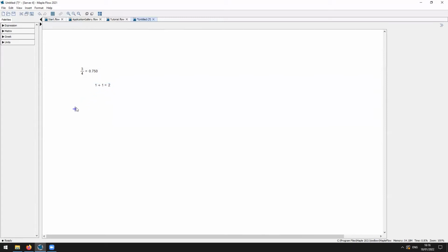So far, I've just created two very simple math containers. I can also create text containers. If I move the grid cursor to a blank part of the canvas, now to start an empty math container, I just hit the spacebar. That creates an empty math container. At this point, I can start typing text. Let's create another one.